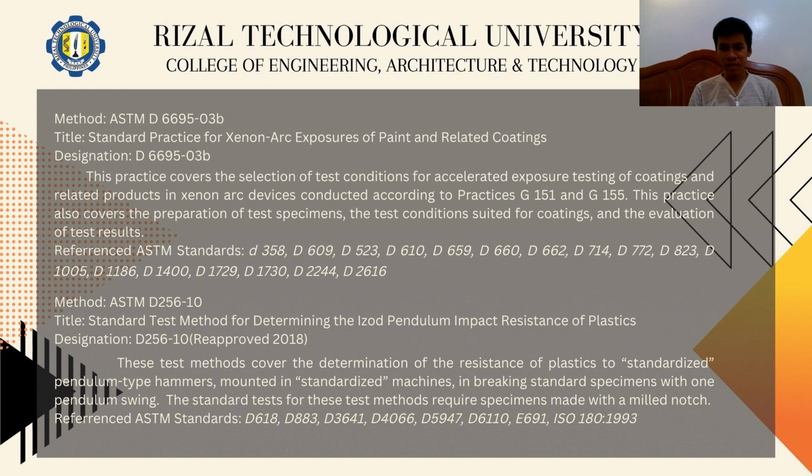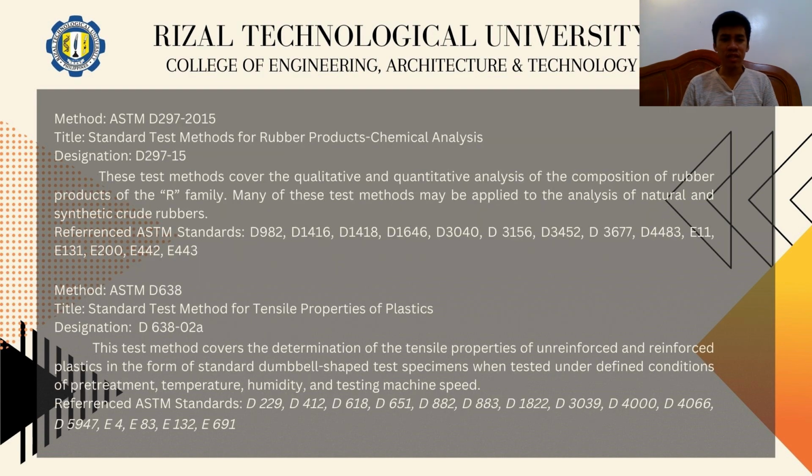Since this method permits a variation in the width of the specimens, and since the width dictates for many materials whether a brittle low-energy break or a ductile high-energy break will occur, it is necessary that the width be stated in the specification covering that material and that the width be reported along with the impact resistance. In view of the preceding, one should not make comparisons between data from specimens having widths that differ by more than a few mils.